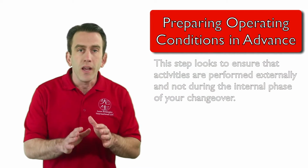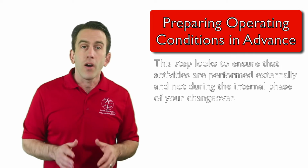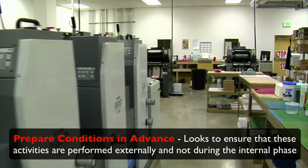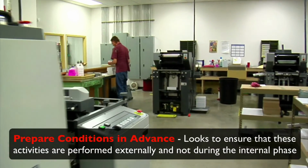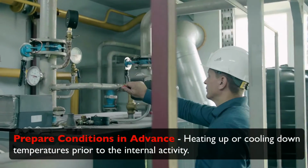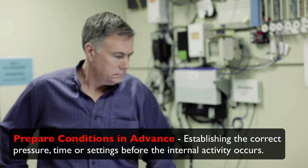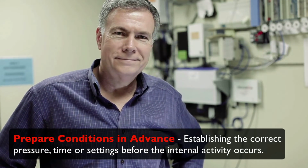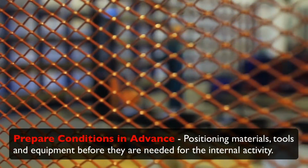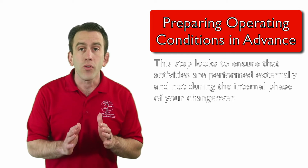Preparing your working conditions in advance of the actual internal activity can drastically shorten your changeover time. As part of the conversion phase of reduce, this step looks to ensure that these activities are performed externally and not during the internal phase of your changeover. Some examples may be heating up or cooling down temperatures prior to the internal activity, establishing the correct pressure, time, or settings before the internal activity occurs, and positioning materials, tools, and equipment before they are needed for the internal activity. All of these activities can be done while a line is still running.